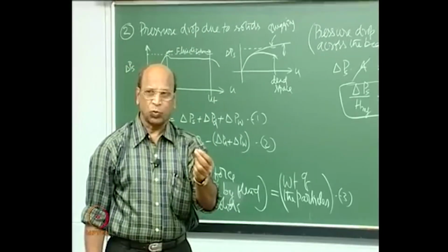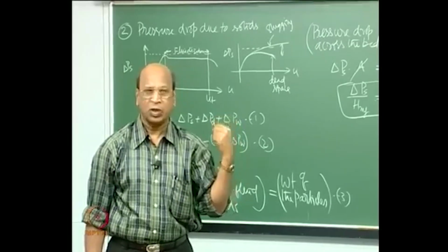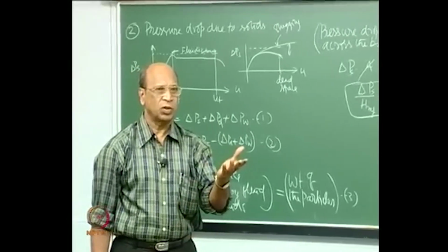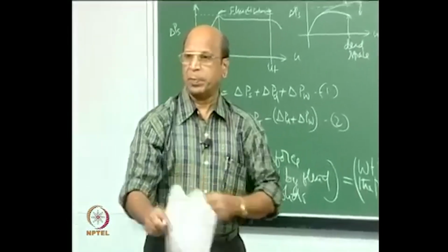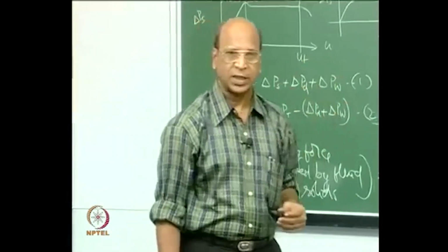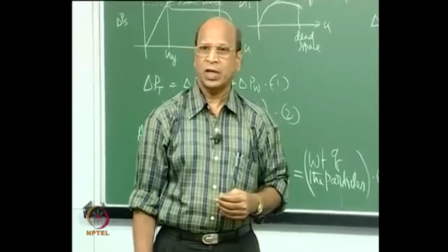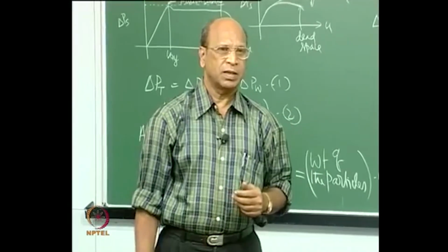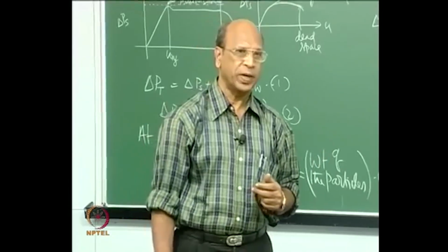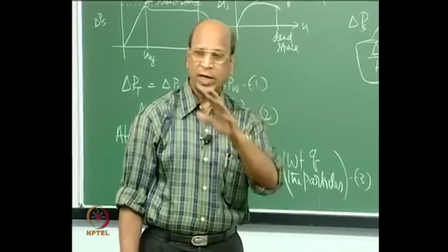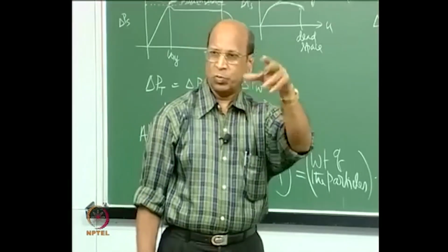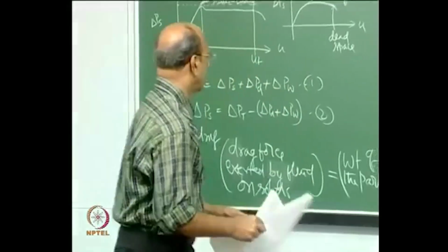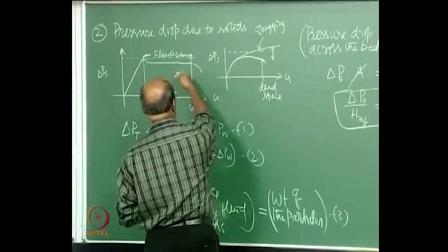So these simple things one can see from the graphs, and then find out what is the disease for this particular fluidized bed. It is like doctors, they will ask you to take some BP test or some other test, and then they see the results or graphs, and find out what disease you have. Similarly, you are also doctors for the reactors or any equipment. You can just find out by drawing or by looking at some measurements whether something is wrong or it is beautifully fluidizing. So, all these simple things will be there when you just plot this.